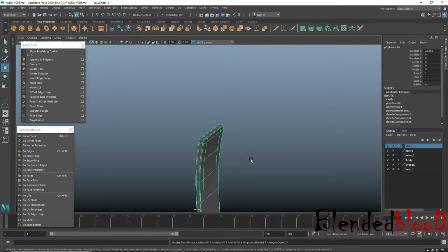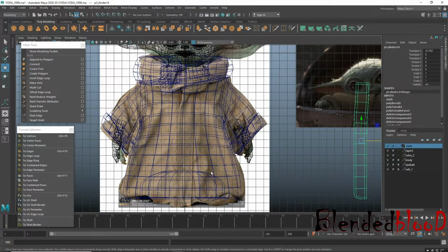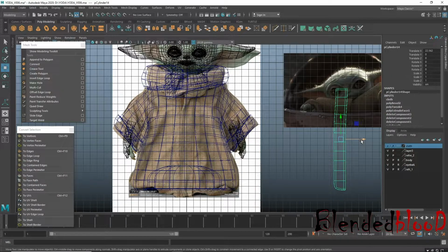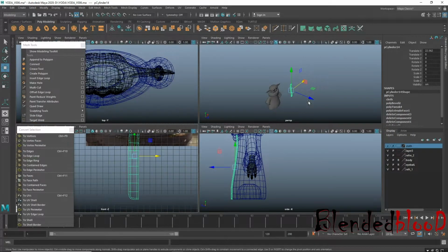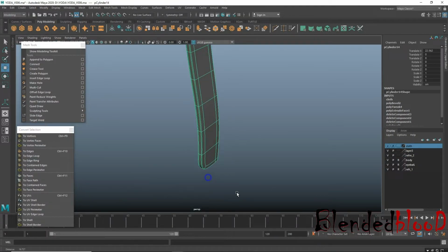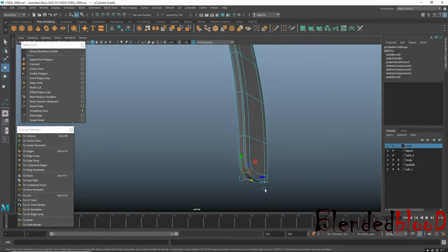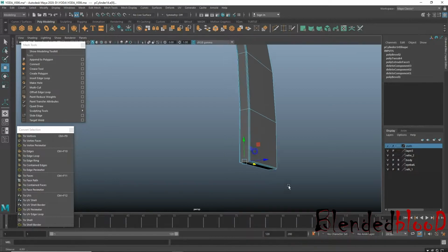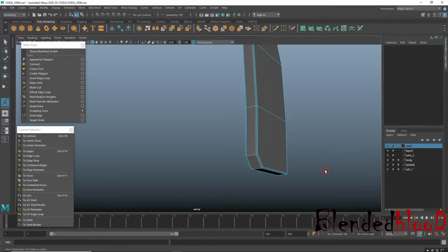If you press 3, this will go like this, and place it from where we extracted this portion. See, we just left one edge, you can see over here. Control D, I need to go back, yeah, see, this one is left over.